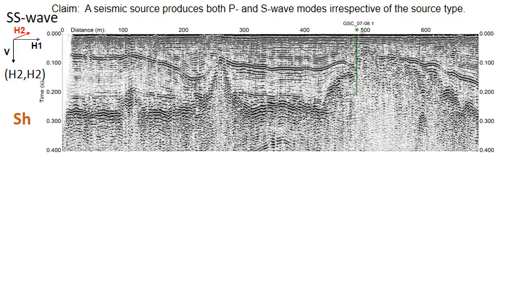This slide shows an SH reflection seismic section acquired with a microvibe source and receivers in H2 transverse mode, where the main strong bedrock reflection is at approximately 25 meter depth to the left of the section. This section shows a remarkable resolution, as much as less than 1 meter in the sediment covering those gravel and diamicton mounds.